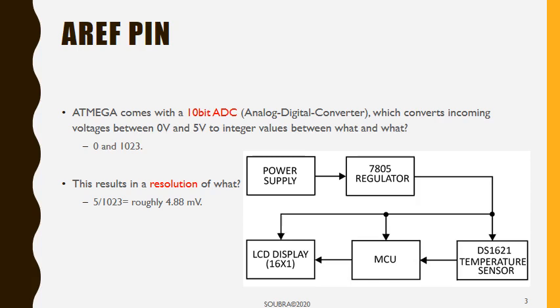Where was I? Yeah. So why would that be problematic? Why, if the sensor is unable to spit voltage between 0 and 5, why would that be problematic? Let's study 2 different cases. What if the sensor, and this is impossible in real life because it would be crazy if manufacturers did that, imagine if the sensor is able to give values between 0 volts and 10 volts. What am I losing here? Half of the readings, I'm not able to follow up with them because to me everything that is after 5 volts is considered to be 5 volts. This is the maximum value I can see. Make sense? And this almost never happens in real life.